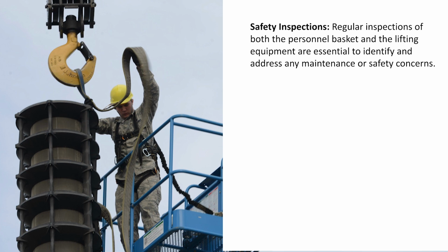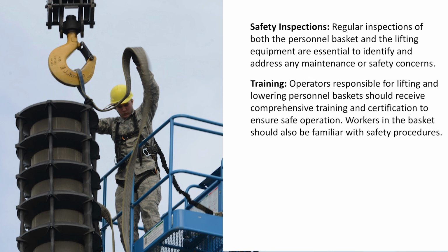Regular inspection of both the personal basket and the lifting equipment is essential to identify and address any maintenance or safety concerns. Training is another important factor. Operators responsible for lifting and lowering personal baskets should receive comprehensive training and certification to ensure safe operation.